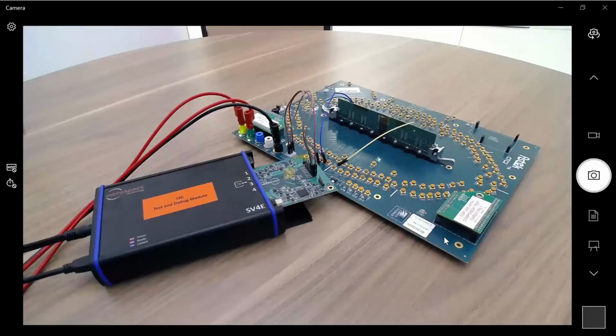Today we continue on DDR5 DIMM sideband bus testing, and we'll cover an important topic, which is the ability to probe a bus that is different from the bus that we're operating on. So if we're testing a DIMM, we are talking to the DIMM through the sideband bus entry into the DIMM, and that's typically connected to a hub device. But what if we want to probe devices that are behind the hub?